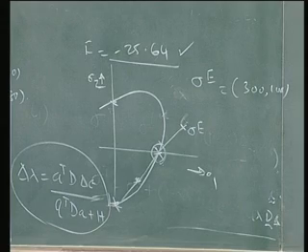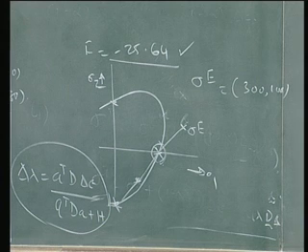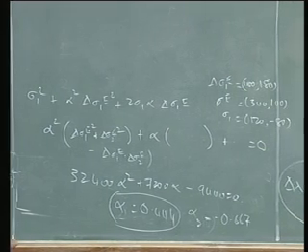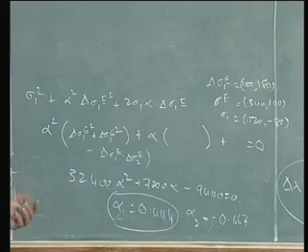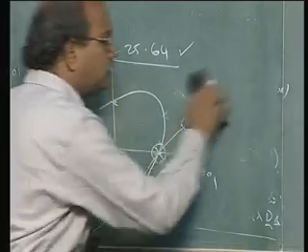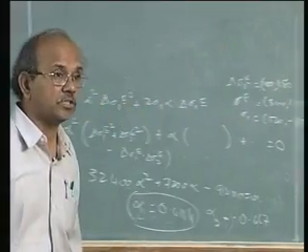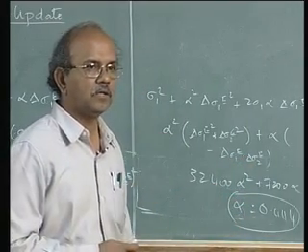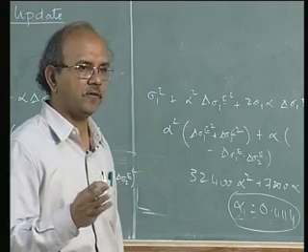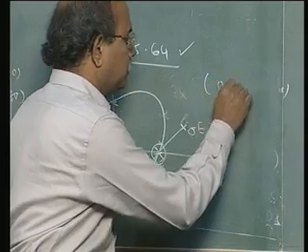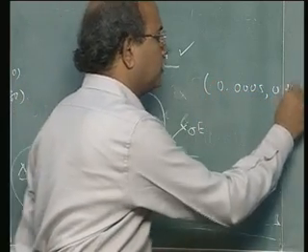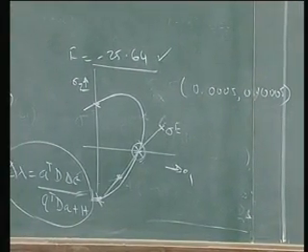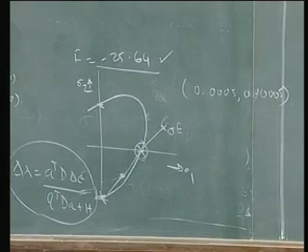Now, even before I go there, using alpha, I have to separate out the delta epsilon into two parts: what I have to correct and what I need not correct. So tell me, what is it that I have to correct? Yes, correct, 1 minus alpha into delta epsilon. So 1 minus 0.444, what's that value? It happens to be around 0.0005, 0.0005, 0.0005. That's the delta epsilon value which I have to now use. The rest has been consumed into the elastic part.